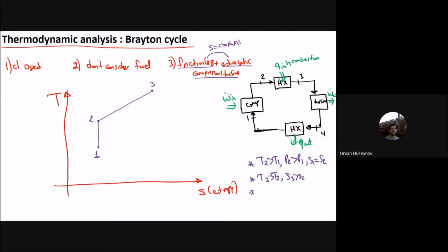Now comes that stage, but you should remember that I should add that to 4. Heat exchangers are adiabatic. Sorry, that is not adiabatic. It's actually adiabatic for the environment, but for the system it is not. But heat exchangers are isobaric. The pressure drop is not considered. Heat exchangers are very essential. These are used in all of the cycles. In all of the cycles, what we begin with is the frictionless adiabatic expansion and compression processes, and isobaric heat exchangers. Now let's do that one. So P3 is same as P2.